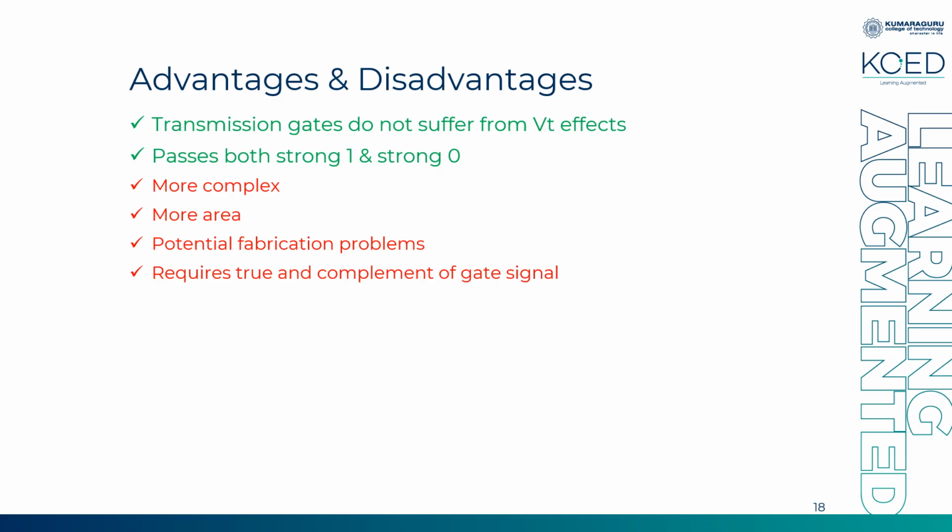So when you see the generation of VDD supply and clock lines, now when you're studying, you have seen it as just a 1 and 0, but generation of clock, generation of true and complement of signal requires separate circuitry. So this is in turn yet another problem or yet another complexity faced when you design any circuit using transmission gate.